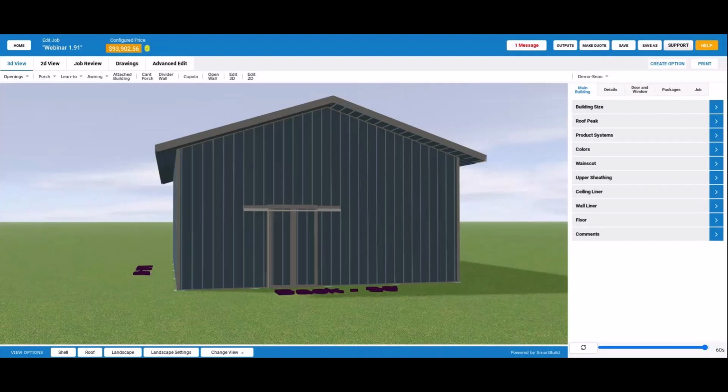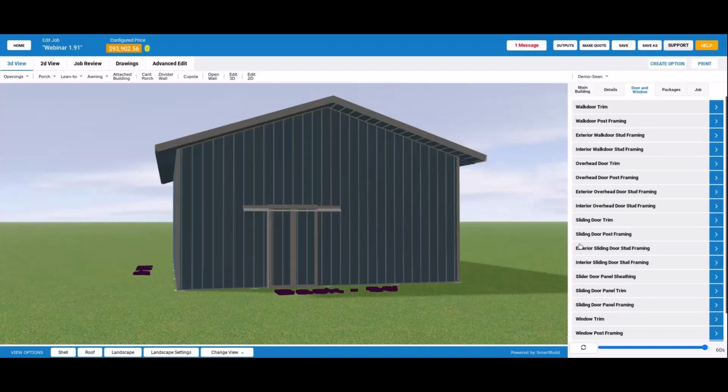If you have a 10-foot door and you only have 10 footers, it'll try to put a 10-foot piece going across there. Or if you have a larger piece, it'll put the largest piece you have and then cut it from there and go on to probably using whatever shortest piece you have. So it should all work with the usages that we have. They're all the same, whether it's the framing part or the trim part, if that helps.